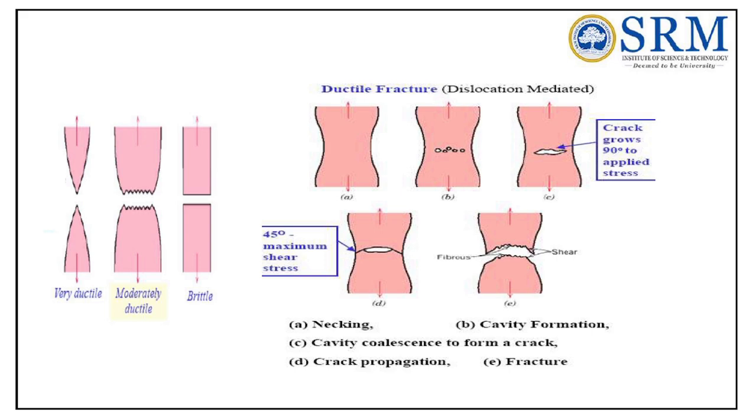Then after some time, when the load is continuously applied, the material loses its strength and allows the tensile load to go predominantly over the internal energy, so that the material starts to yield permanently. It continues until it reaches a point called the ultimate tensile point. Figure B shows where the small voids form. After the material reaches the ultimate tensile stress, it is no longer able to withstand the stress, so a small neck will be formed.